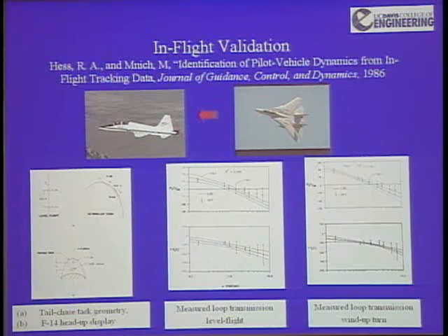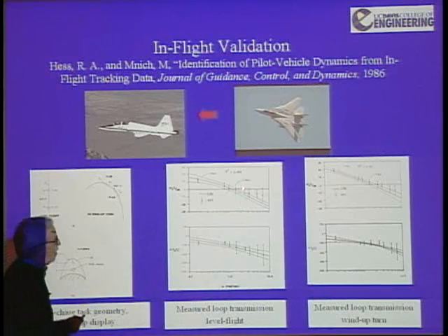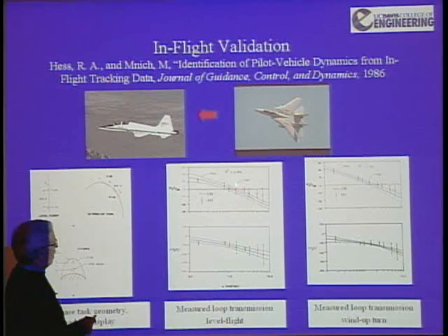Okay? And so Mark went ahead and measured the pilot vehicle dynamics in the wind-up turn and level flight. There are the results with two measurement techniques, fast Fourier transform, and another one using output error estimation. 20 dB per decade, 20 dB per decade. We noticed on this, by the way, that the crossover frequency for the level flight was considerably lower than the crossover frequency of the wind-up turn.